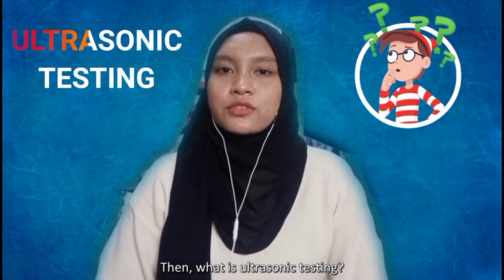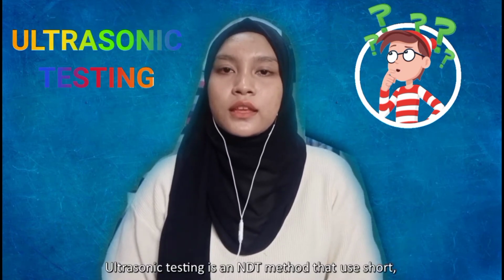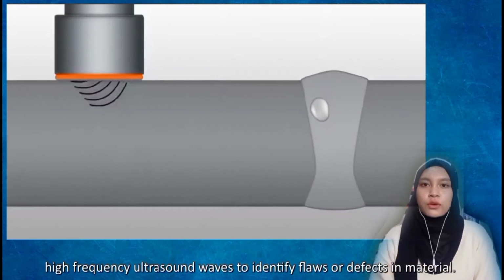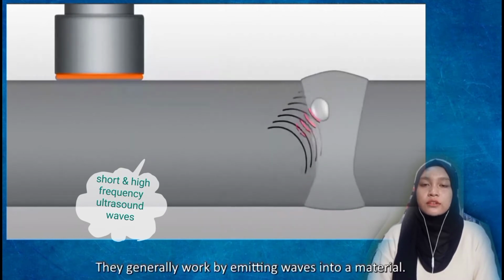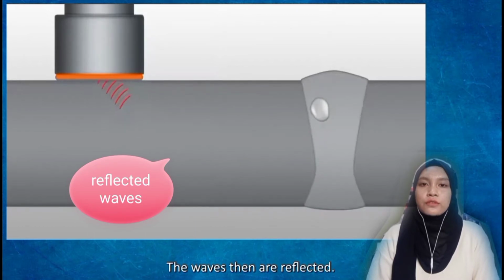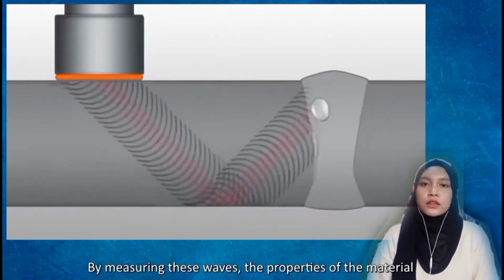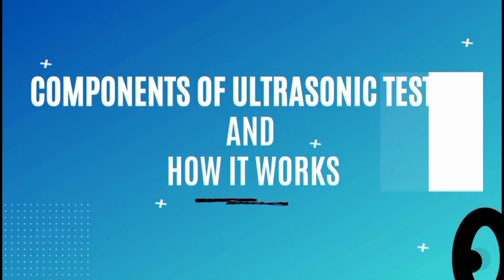Then, what is ultrasonic testing? Ultrasonic testing is an NDT method that uses short, high-frequency ultrasound wave to identify flaws or defects in material. They generally work by emitting waves into the material. The waves are then reflected. By measuring this wave, the properties of the material and internal flaws can be identified.